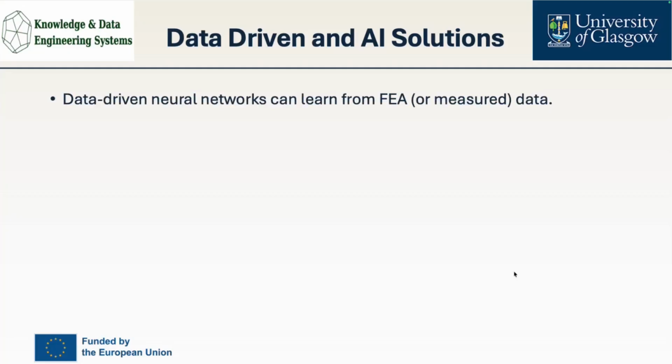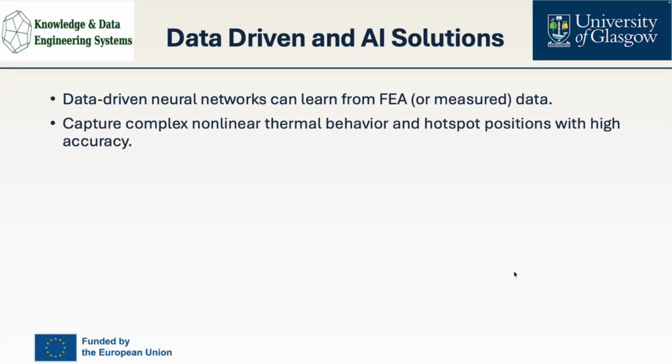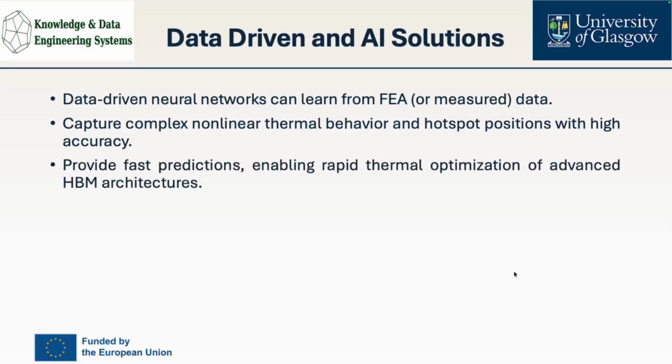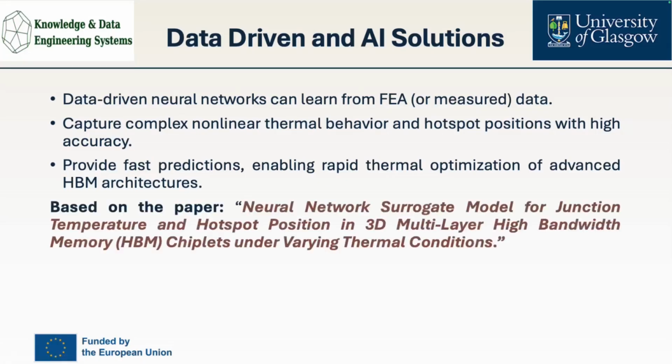A data-driven approach with a neural network can learn from the finite element analysis data to compute complex non-linear thermal behavior and hotspot position with high accuracy. It can also provide fast prediction to enable thermal optimization of advanced high performance memory architectures.